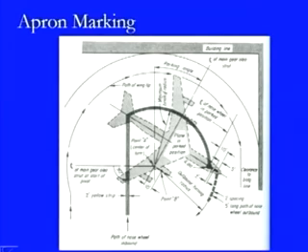So, when we are looking at this type of maneuvers, then this aircraft location, as shown here, will be depicted on the pavement surface in yellow color, and then this type of path of the nose wheel for the inbound condition or outbound condition. So, this is the path of the nose wheel. First of all, the aircraft will come in this form, and then it will start taking a turn. So, this is how it will be taking a turn and will become in this condition. So, once it has done this, this is how the nose wheel will be moving. It will be in the initial condition here, and then as it starts taking a turn, it will be taking a path like this.